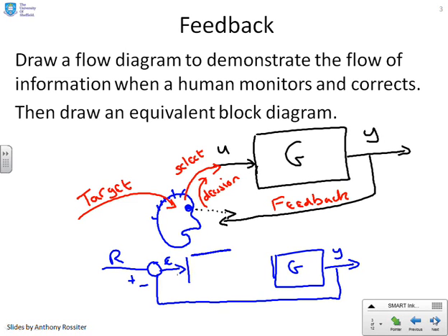And then what you do is you come up with a decision. So I can't write it all in there, but if you imagine that box says decision, and that decision says, given the error that I've just observed, what input should I choose into this process? And you'll see that this is a continuous loop. So you're continuously monitoring the output, generating the error, making a decision, modifying the input. Okay, and therefore we have our standard feedback loop.